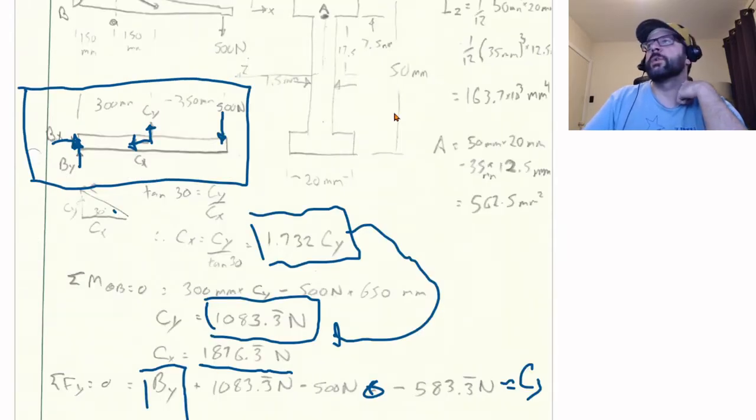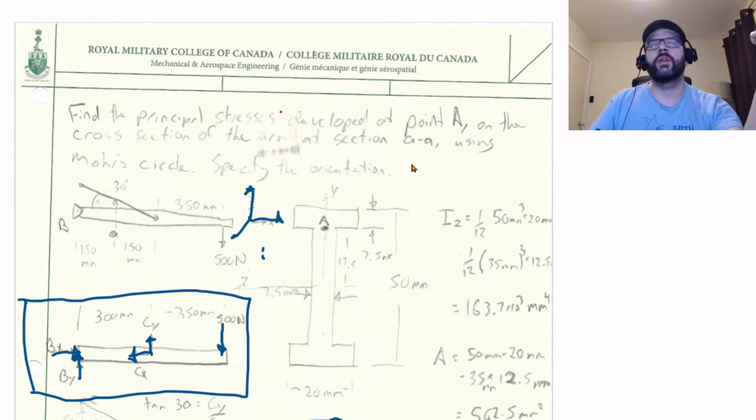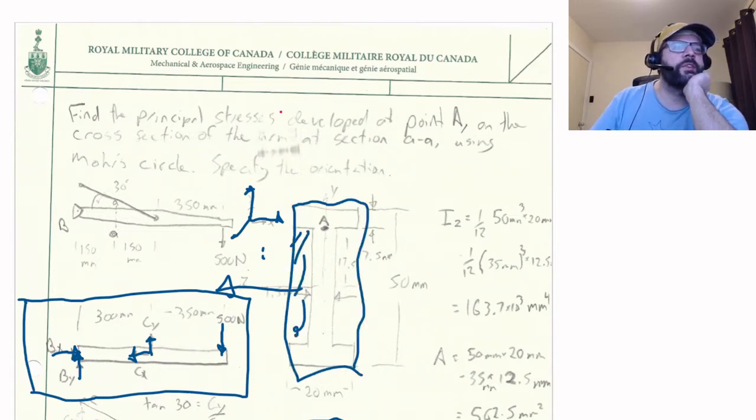Also did a few calculations on the cross-sectional area. So we know that we're going to need to figure out its Iz. So again, using the usual coordinate system that I like to use, x is along the length of the beam, y is vertical, so z is this way if we're looking at the cross section. So Iz is just going to be equal to the I of the overall thing minus the I's of this cross section here.